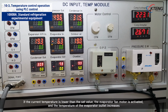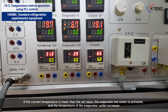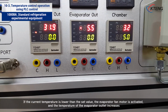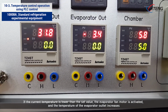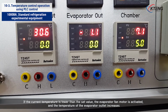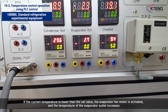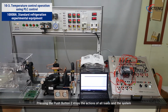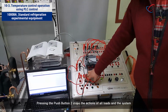If the current temperature is lower than the set value, the evaporator fan motor is activated, and the temperature of the evaporator outlet increases. Pressing the push button 2 stops the actions of all loads and the system.